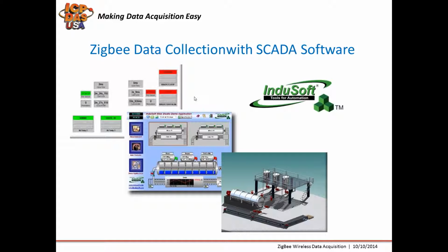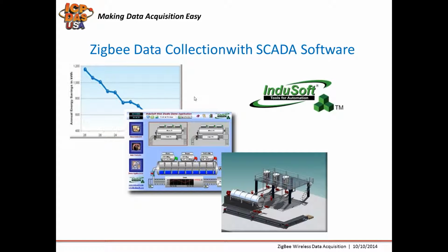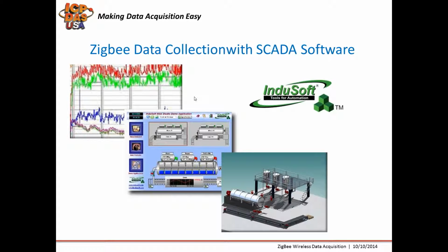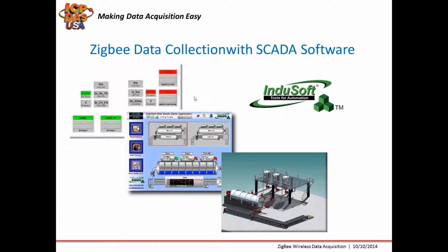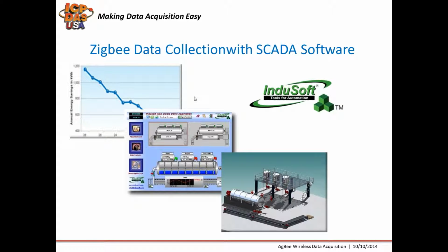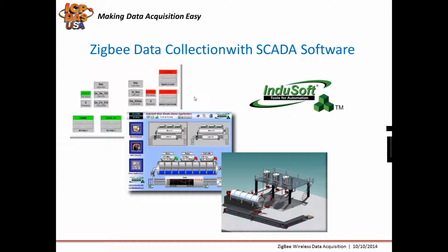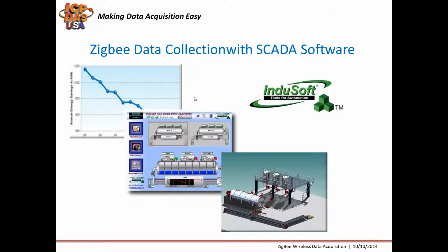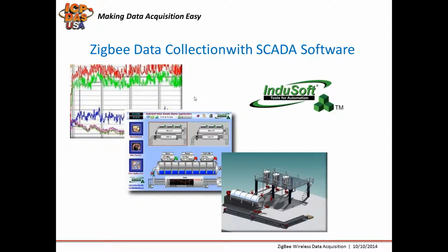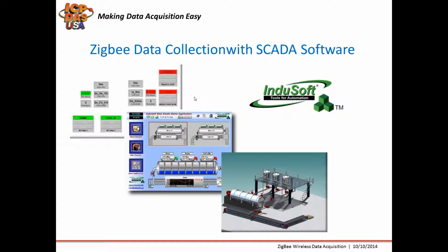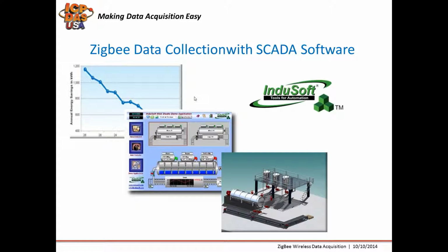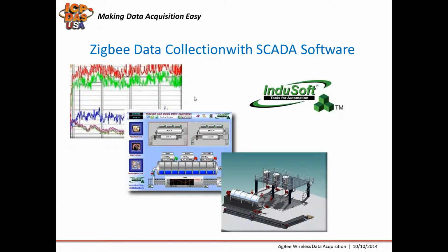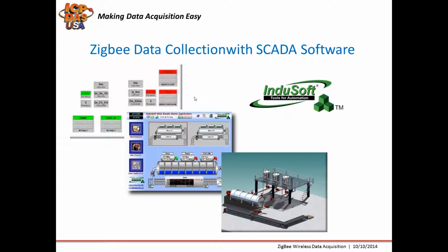Administrator users, for example, could have access to make changes, and operator users could just see the status of the system. SCADA software can be used to generate customized reports, so you can configure the system with print buttons so you can print the customized reports out, or you can save them as a PDF. InduSoft supports multi-languages, so you can easily change the language in your system.